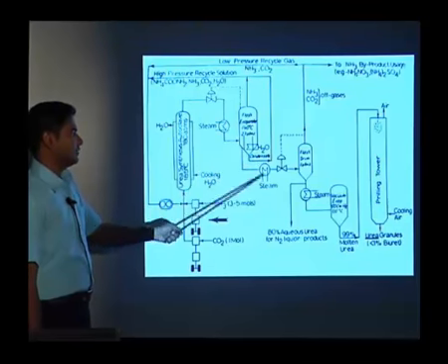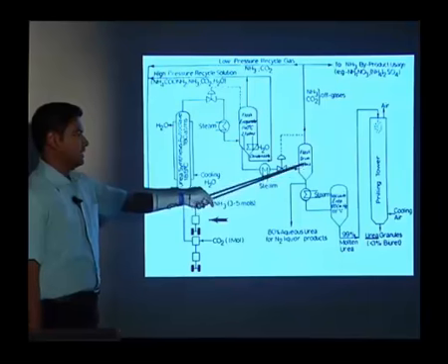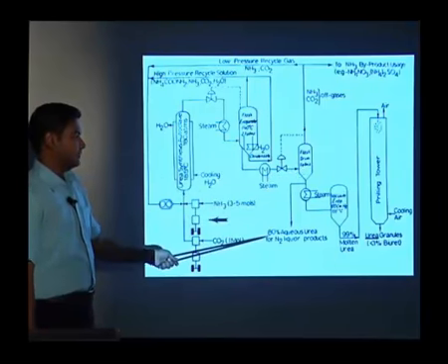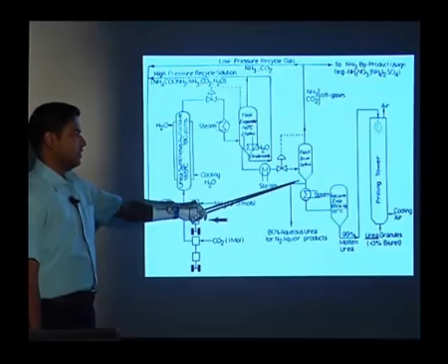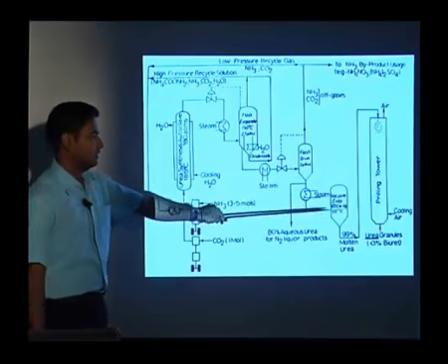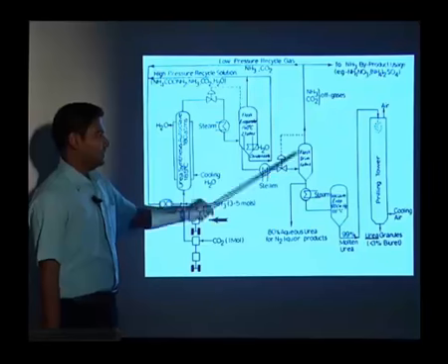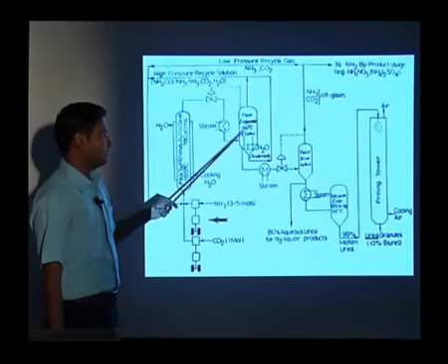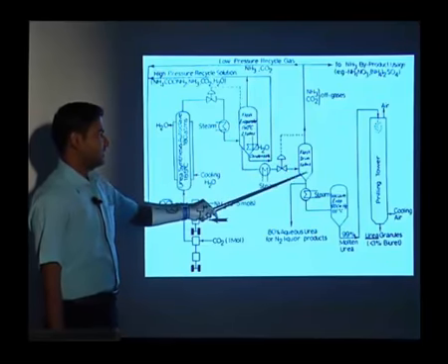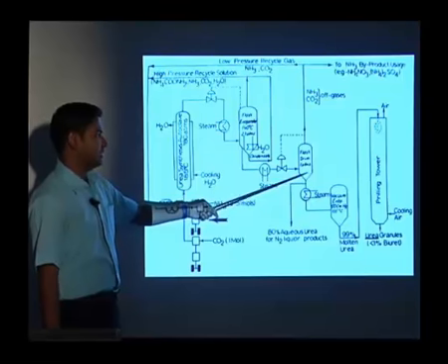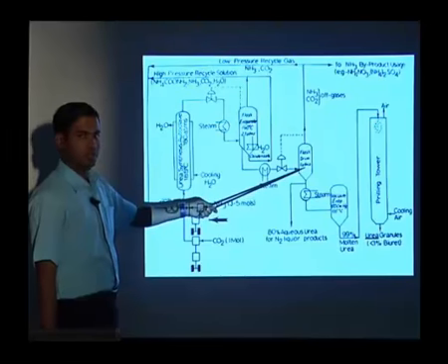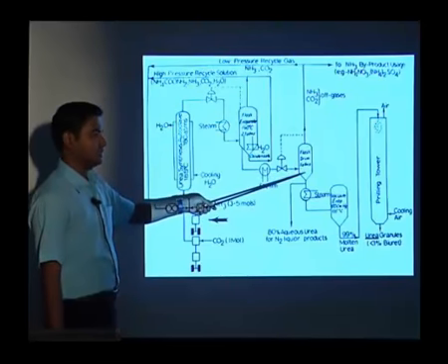From here it will go to the flash drums, where we can have the 80% aqueous urea for nitrogen liquor products, or we can have it in another vacuum evaporator at 60 centimeters of Hg and 135 degrees Celsius. So it is already flash evaporated, and then we can have the flash drum at 1 atmosphere for the decomposition.